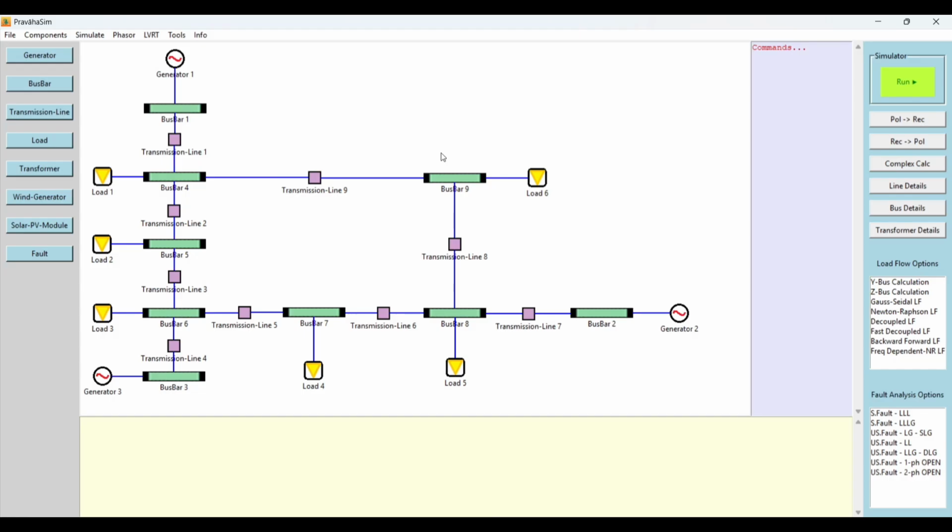This is helpful to check frequency stability under different load demand conditions, and the user or analyzer can take different actions based on these frequency changes. For that, first we have to select one load. Let's select load 5 for that purpose. Now in load 5, select the dynamic load series option.